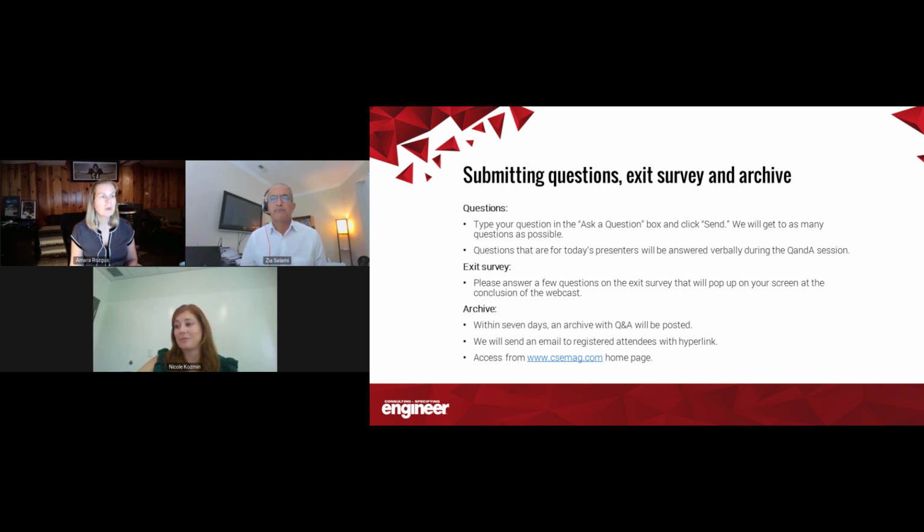Great. Thank you, Nicole. Zia, this next question is for you. What are the most common errors when designing a UPS system? Good question. The most common error, to me, is sizing the UPS based on the initial or existing load and not considering the future demand. Load and demand increase, and that is not considered if we start with the initial and existing load. That's a typical error that I see.